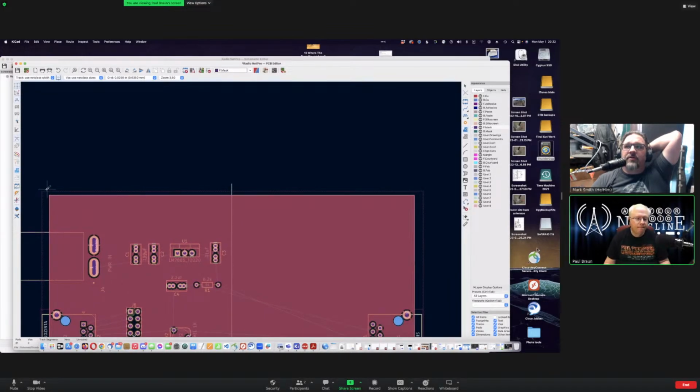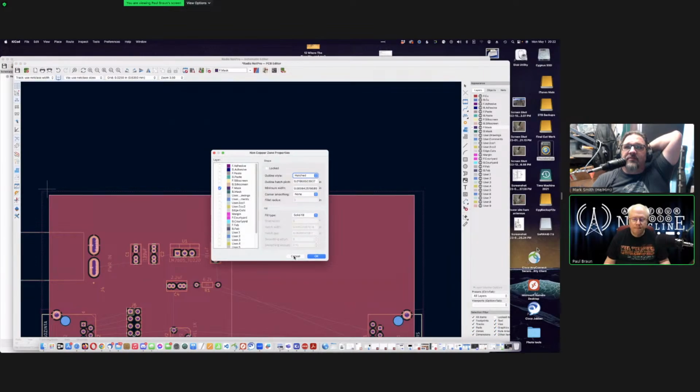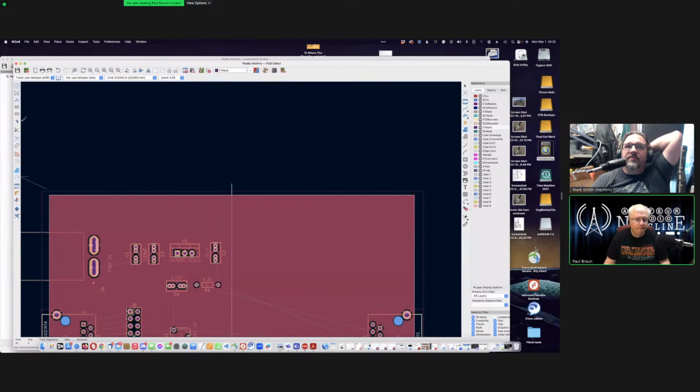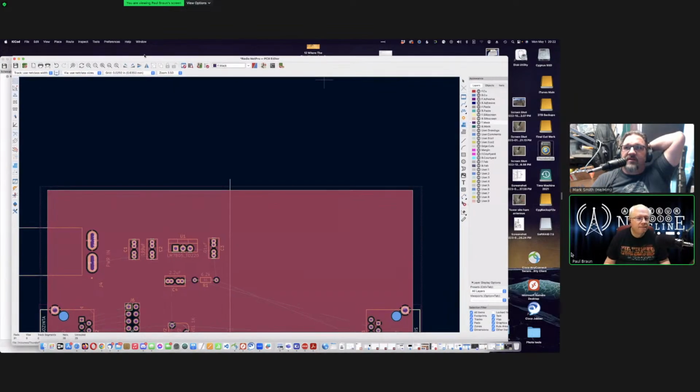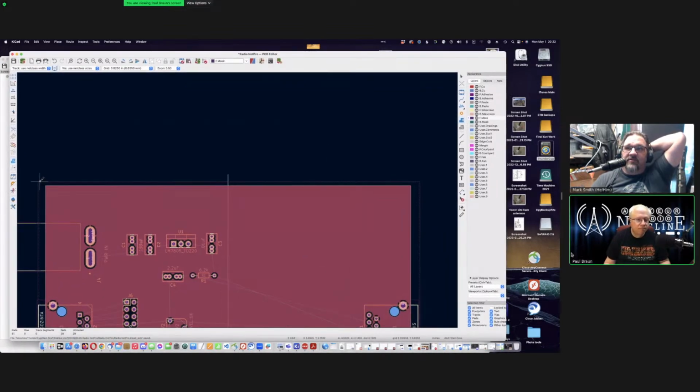Click in the corner. And then select both front and back mask. And hold on. Solid fill. Oh, okay, that's fine. Yeah, go ahead and do that, and then bring it down 0.1 inch, 0.05 inch, something like that. So you'll have to figure out what the top edge of the board is. It's not critical. The exact dimension isn't critical.